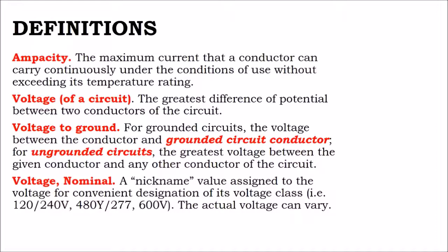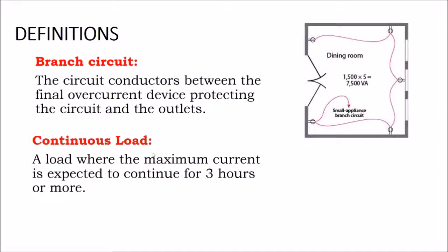And then, you also have to consider your operating conditions as well. And that might mean that, sure, a solar array is going to be operating at 30 volts on its spec sheet, and that would be considered the nominal voltage. But its maximum voltage may be something different. Its maximum voltage may be a function of temperature. And so we have to apply temperature correction factors before we get into our design to make sure those conductors don't burn up.